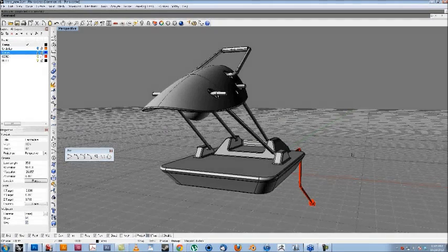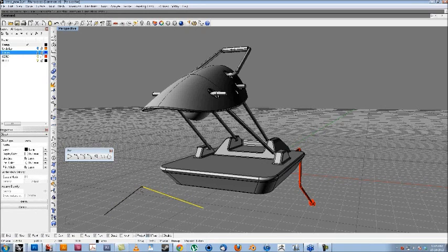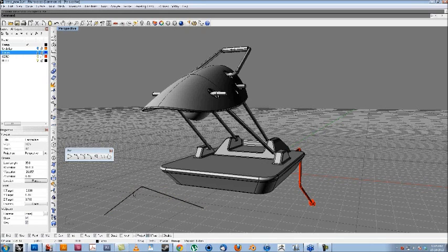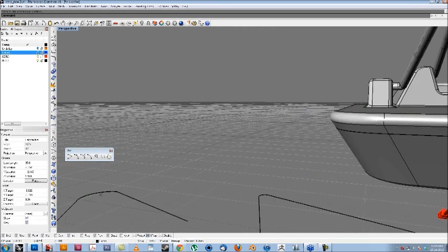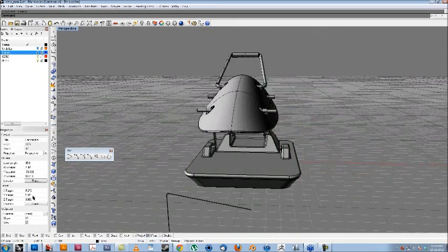I don't think there's much of a difference. So if I have a curve and it's got a kink like that, if I fillet it, what it's going to do is it has to rebuild that as 3 curves, so you still have to join it. If you were to build out a curve and then build out another curve and then put an arc between them, then you have to match them. And so, I mean, it's really a preference. I really do think you're only saving a matter of seconds at that point.